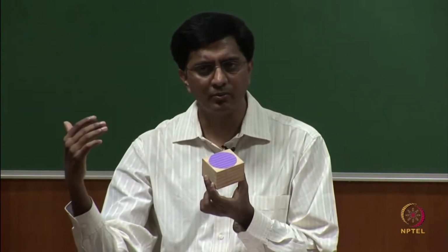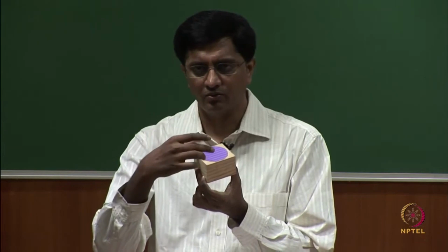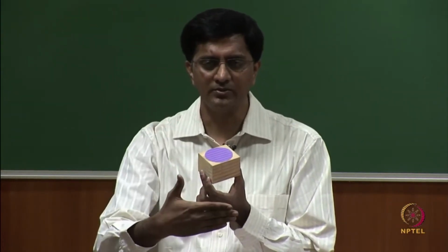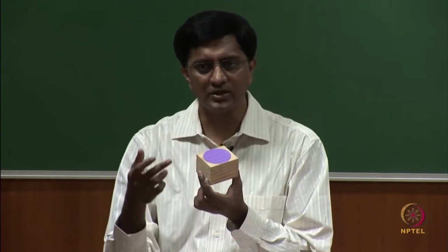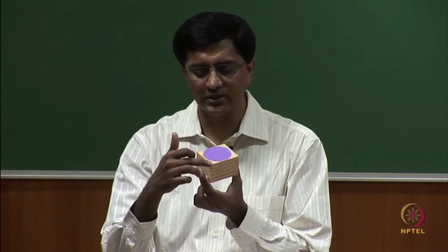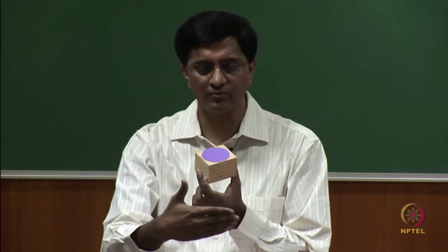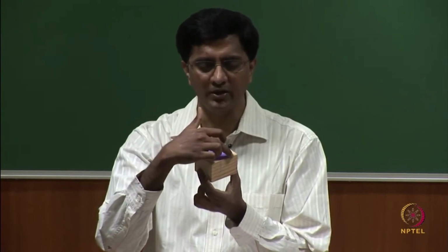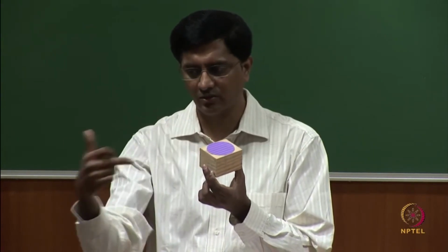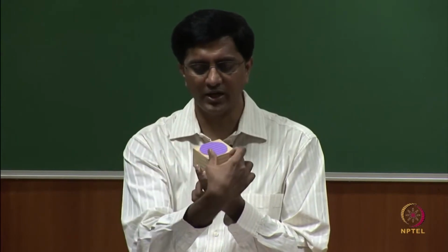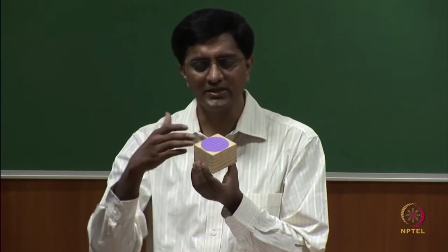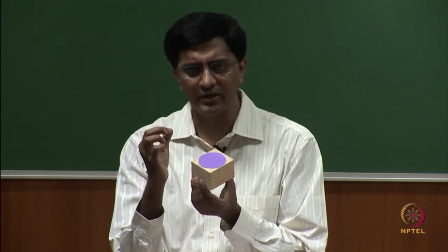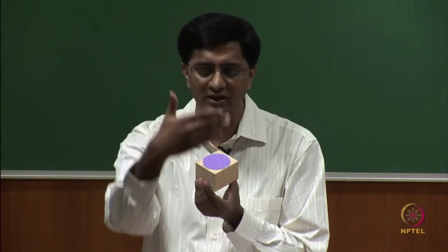We have a principle, right? We said we can capture true length if the feature we are looking at is parallel to the projection plane. So, now let us ask the question in this way: is this edge parallel to the projection plane? No. Are any of the other edges parallel to the projection plane? No. If this is the front view, this is the width, depth and height, none of them is parallel to the projection plane. So, now let us try to identify if there is any feature on this which is parallel to the projection plane.